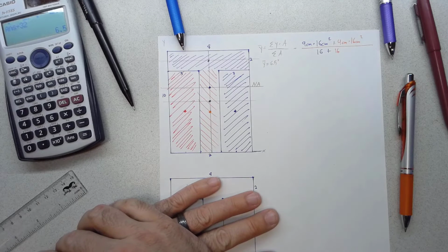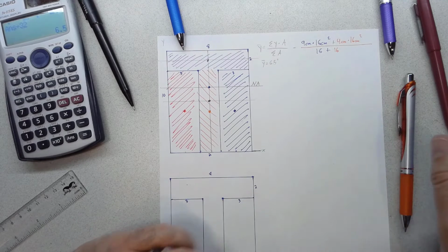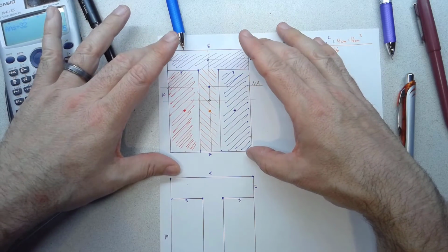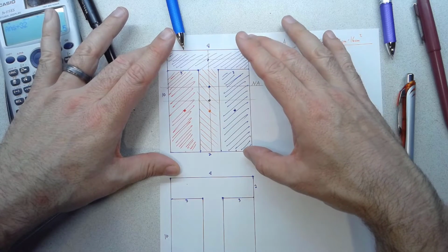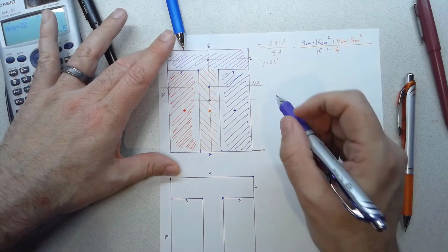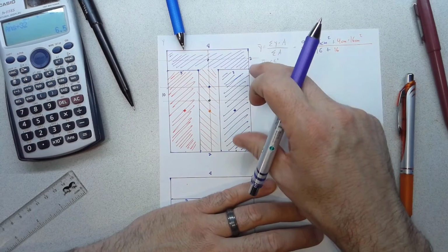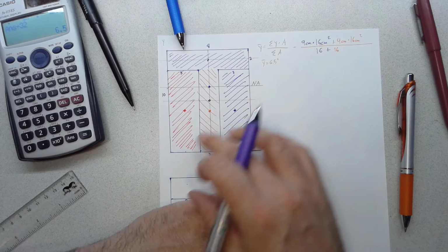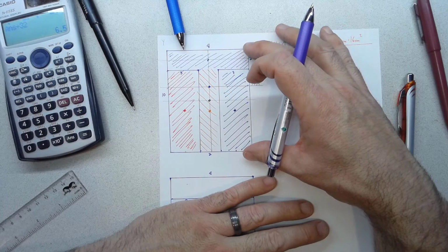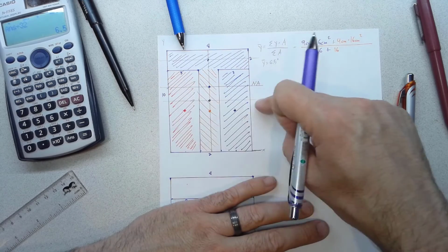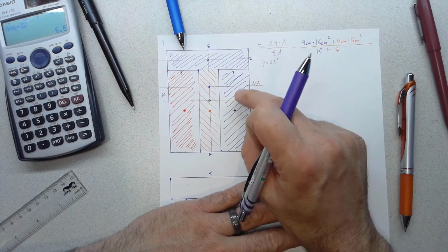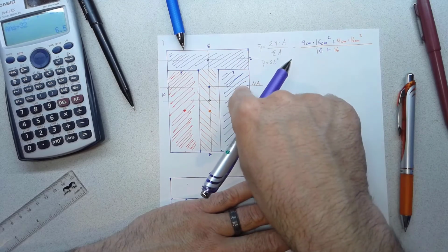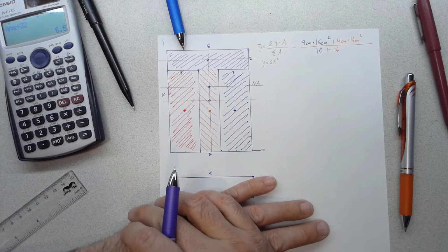Okay, now that we have y bar, we can start looking at I. If you think back to the I of the total rectangle, that was 666.66. You might think that what we're going to do is take that I and subtract out the I's of these individual pieces. But we actually can't do that, because that 666 was I about this neutral axis. If we wanted to do that, we would have to find out what the effect of this area was about our new neutral axis. And we'll look at that maybe in a minute, do it that way.